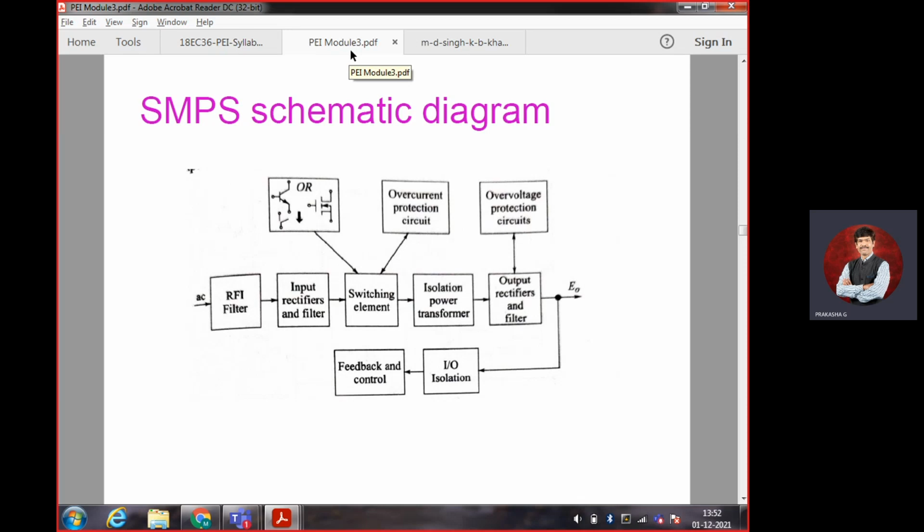So we are not going to convert AC into DC outside and then feed the TV. The AC will be given to the stabilizer, and the stabilizer will give a stabilized AC output. There should not be any fluctuation. As I said, 210 to 230 volts, or 240 volts, that fluctuation should not affect your refrigerator, TV or some other device. So the stabilizer converts AC to AC, keeping a constant output.